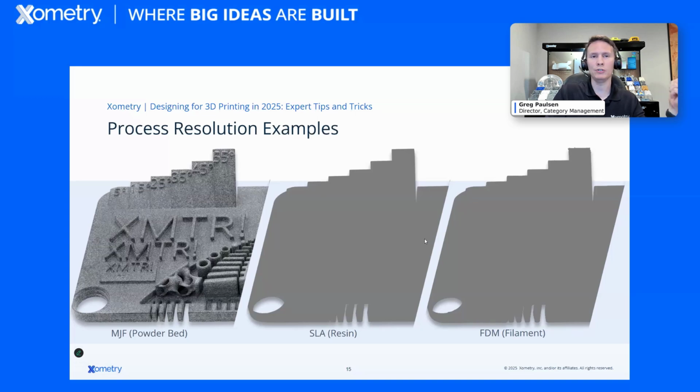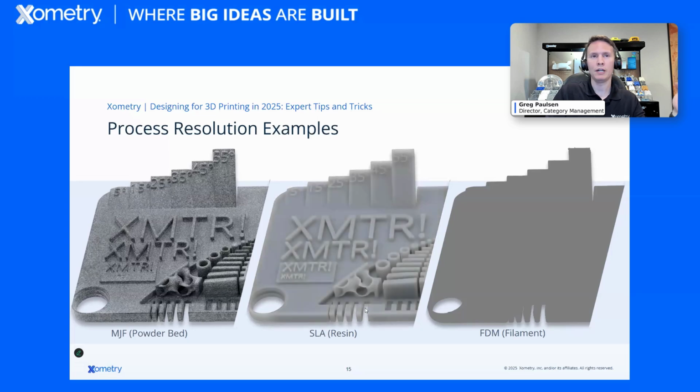When I look at this compared to a liquid photopolymer, I have much crisper details. In this case, again, that's 10 millimeters, 15 millimeters, 7.5, and 5 here. But you can see that the smallest text actually did resolve in this. I don't recommend making all your text like this, but you can get away with it better in SLA. You can see that you have much crispier features from the get-go with this process. So better feature detail resolution.